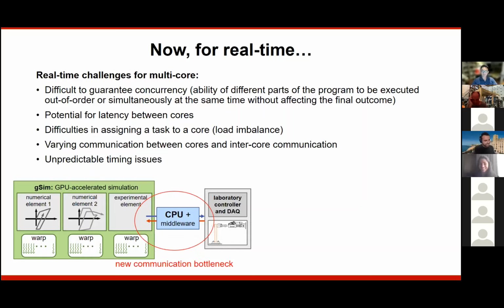One other question is, we've migrated towards explicit schemes primarily because of exactly what you say. Especially for highly nonlinear problems, it's very difficult to formulate the stiffness matrix, and it also takes time. On top of that, the iterative Ax = b, you really can't avoid that, and you can't leave unbalanced loads there. If you try to carry them over, it's going to create noise. So the issue about explicit schemes that are conditionally stable is that numerical controlled damping is very important because of the effect of the state change within the time step.